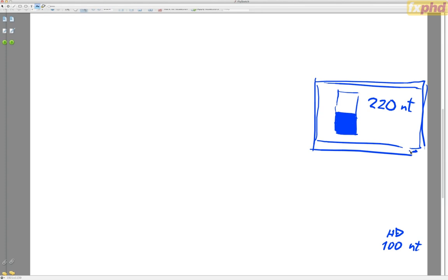Unfortunately, there's no standard for this at this instant, but that's the common practice for HD mastering. Now, if this is a consumer display in a somewhat bright ambient environment, then you might get a black reading of 1 nit. That's partially because there's ambient light bouncing off the screen and raising the black level, partially because the LCD itself doesn't completely attenuate the backlight. So you're going to get some light coming through that pixel. You'll also get some light being bounced off the front of that pixel.